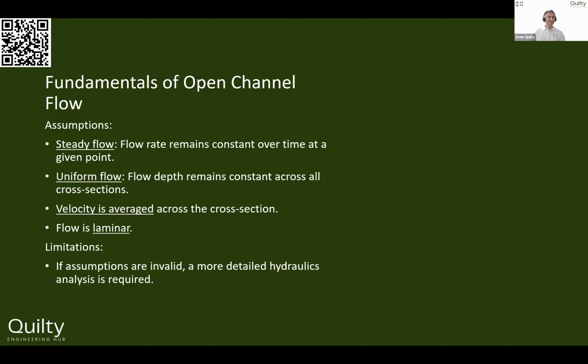Now, if any of these assumptions are invalid, if any of these are not true in your particular case, then you really should do a more detailed hydraulics analysis. That's where you might do flood modeling or even a 1D analysis using HEC-RAS, for example, to see how that flow is going to change over the length of your channel. But we're going to keep to those assumptions for the calculation that we'll look at now.